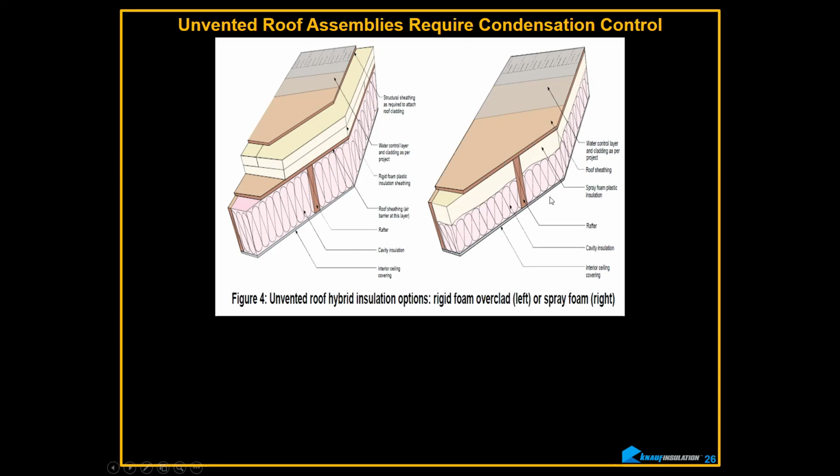The drywall on the bottom has to be airtight. That means you have to seal all the edges of the drywall, and you have to seal the top plates, all top plates, interior and exterior, because you don't want that connection into either an open attic assembly or where a wall might run all the way up to the underside of the bottom of the rafter if it's a cathedral or a vault. As long as this is airtight,